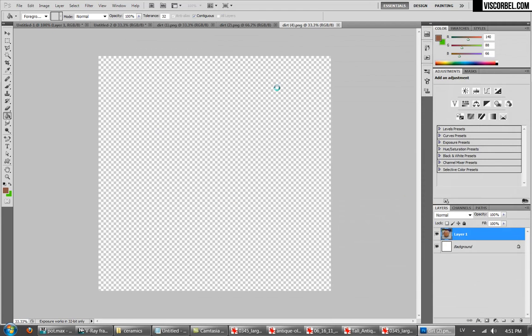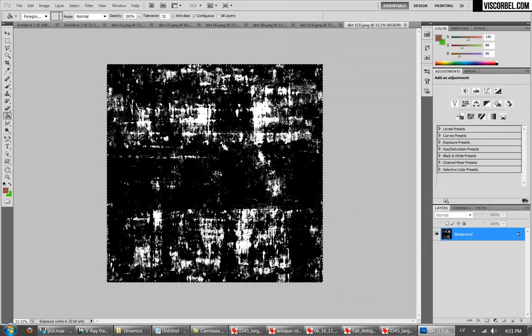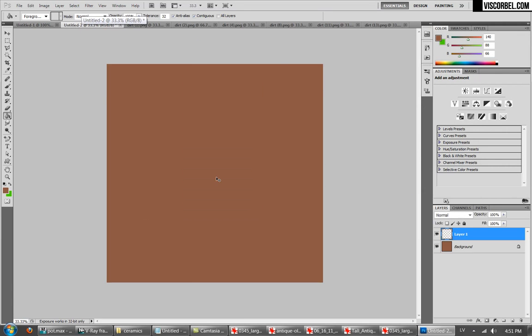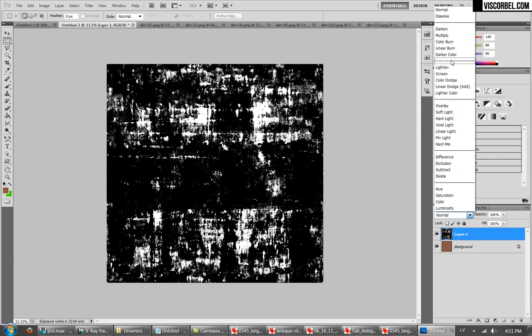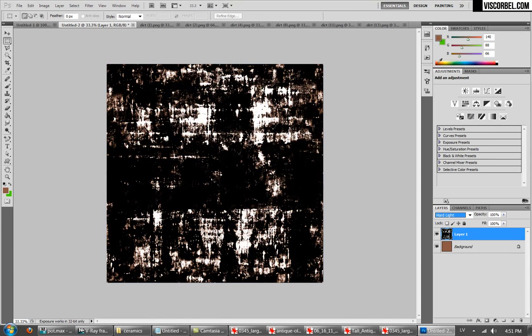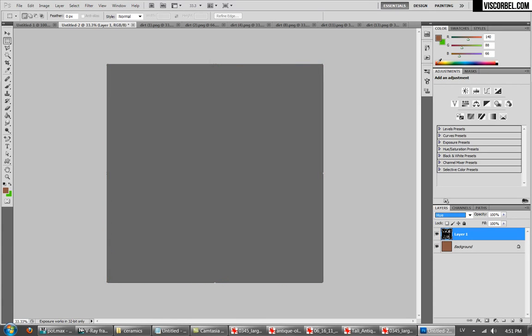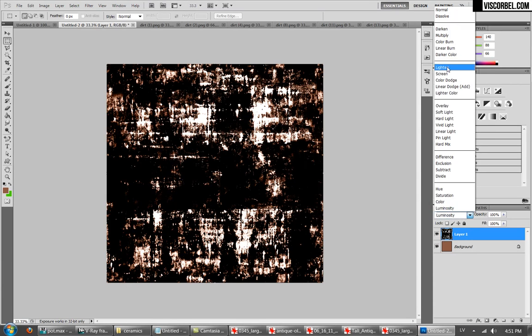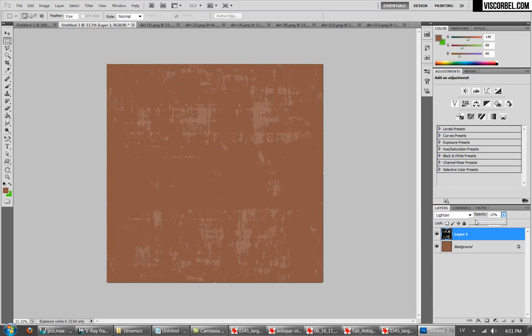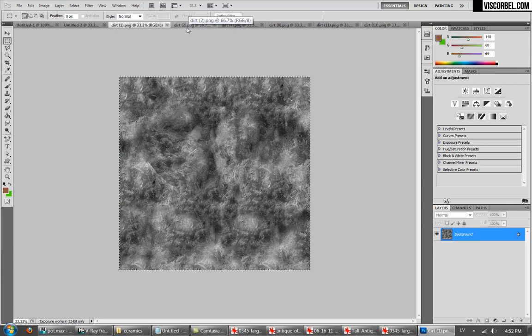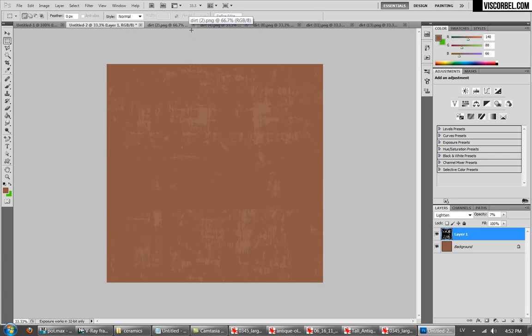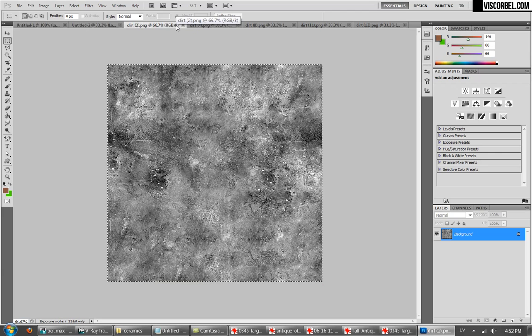All right. Right, I'm gonna take this and I'm gonna paste it over my image. And since these masks are tileable, I'm just gonna make sure the size fits, and it should tile pretty well. And let's make these patches a bit lighter than the rest. So let's set that to lighten and reduce the opacity down to something like 7%. Right, maybe let's add some, okay, this one doesn't work that well. Okay, this one might be better.